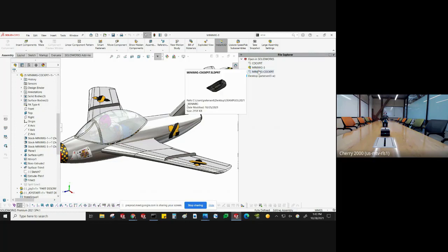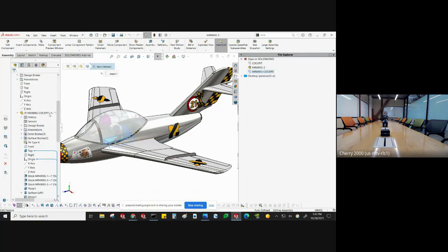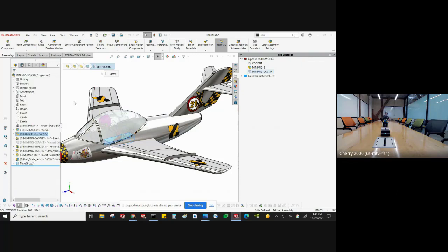They're just trying to get people to be more comfortable in this, because you figure if you expand a part, that's because you were hoping to get into editing one of the features of that part. And now that this part has been solved, I can work on just this part and not have to load everything that's around it. So if you do want to make changes while you're in the assembly mode, you certainly can do that in the lightweight mode.